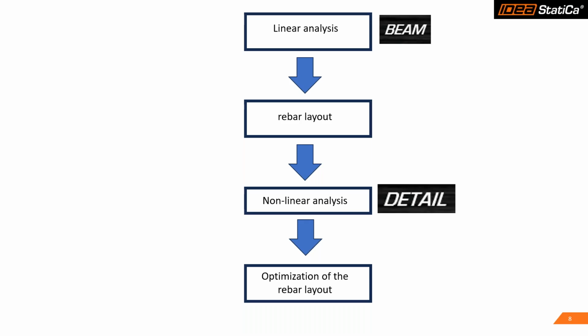If you work with a program for global analysis, then you may have your own favorite 3D program. Our proposal is to work with BIM, because it is a program that is used by thousands of engineers worldwide, and also there is a connection between BIM and Detail. BIM works with BIM elements. Unfortunately, we see younger engineers that try to conduct global analysis with Detail. So this is the right way to work. Do not forget, first the linear or the elastic analysis, and then afterwards the detailing. And with the detailing, you can optimize the rebar layout.